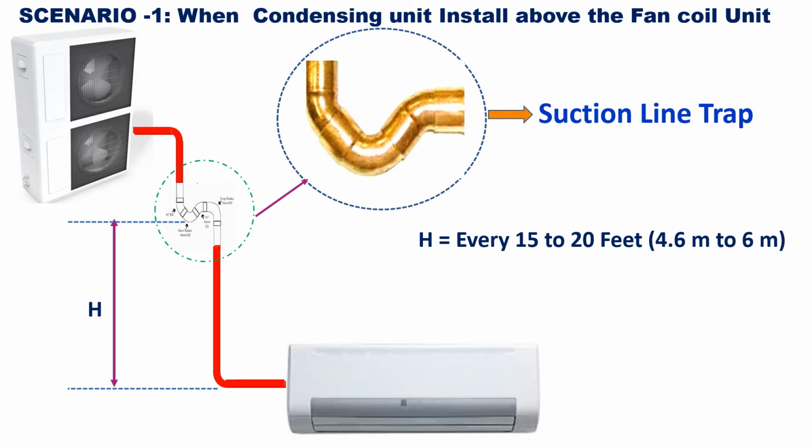During low suction pressure operation, at the end of a cooling cycle, the oil will tend to separate from the suction vapor and cling to the surface of the piping. It will drain back to become entrained in the evaporator during off cycles. The oil trap will collect the oil, and, when the compressor restarts, the higher suction pressure will return most of it to the compressor.